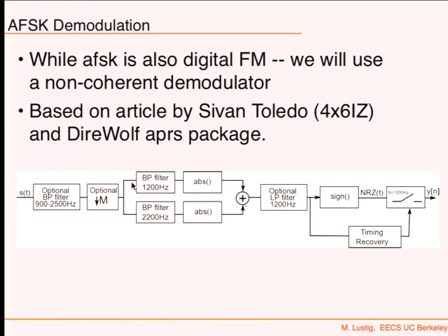Okay, so when you have that signal that has the frequency of 2200, and then you take the absolute value, what's the new frequency? So it depends. Like what's the bit rate, right? So the bits can change at a rate of 1200, and that's why the frequency after that will be 1200. Because the envelope changes at a rate of 1200. This is an envelope detector, right?